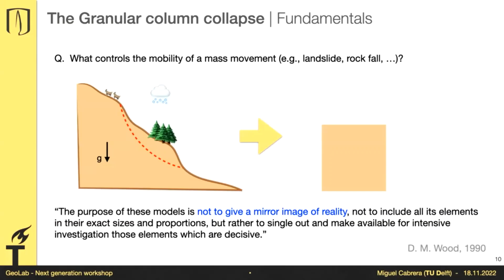But bear with me, and let's accept that the simplification of this problem can be a box or a square that will show eventually a failure plane, and that failure plane will remain the same because it's a frictional material, or it can have some cohesion, but the failure plane does not change because of the geometry of the problem, it's just because of the material. Therefore, if you change the geometry of the problem, you're just changing how much mass it will displace.